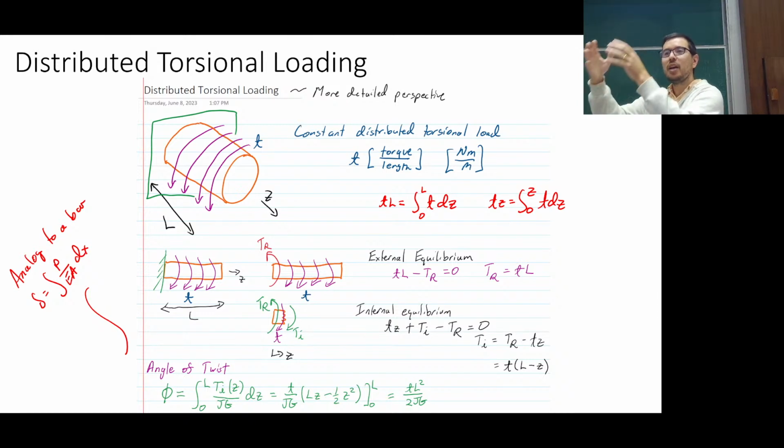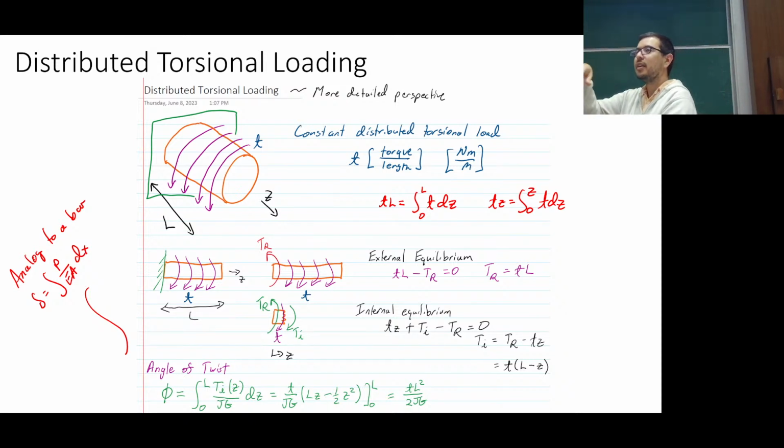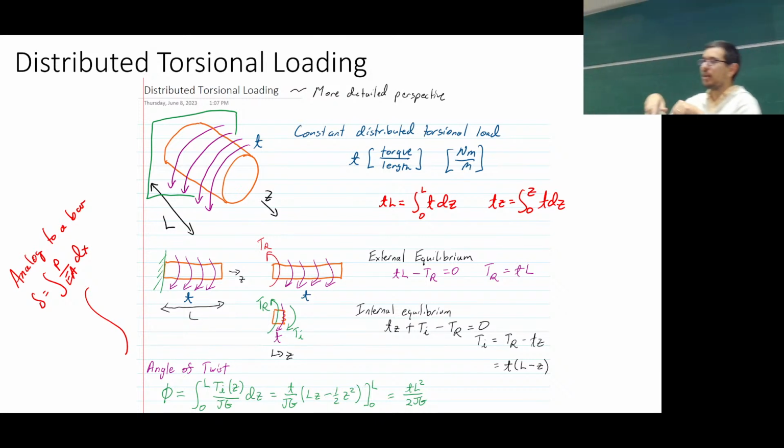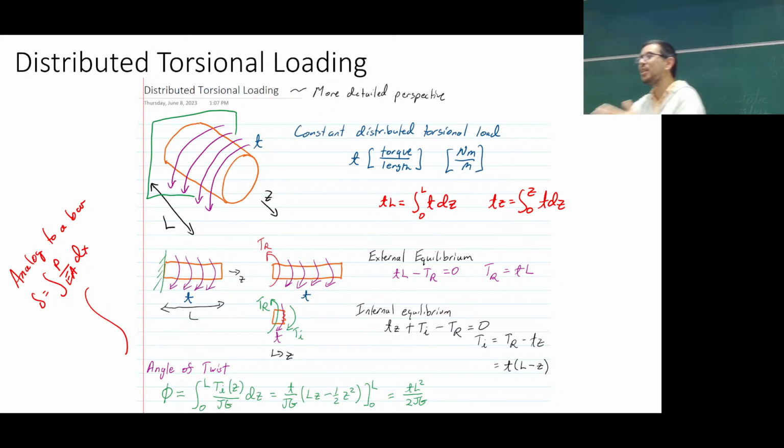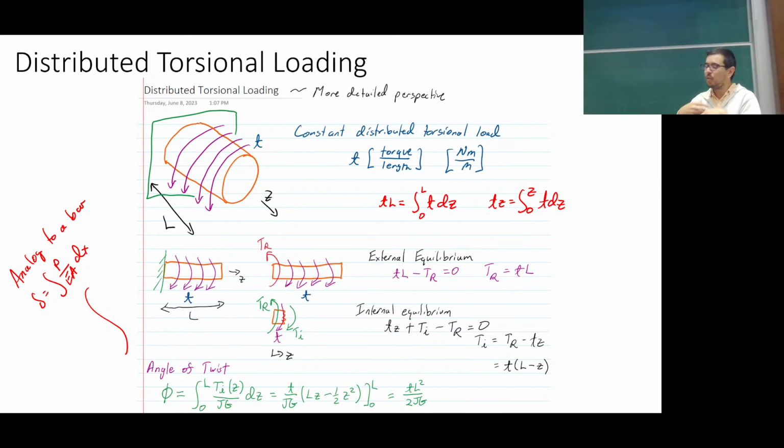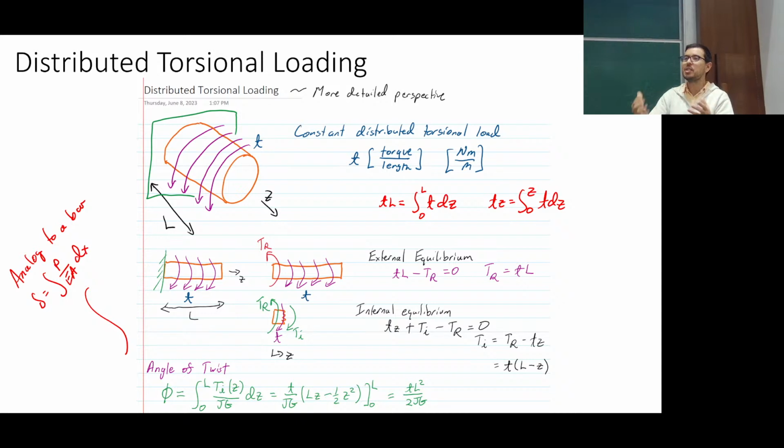If I have a bar, how do I calculate the amount of force that I have to hold it from the ceiling? Yes, Chet. Yeah, you need the length of the bar, yes. You need the weight. Yeah, you want the weight of the bar, just the weight of the bar, right? So it's mg, or it's rho times the volume times g, right? That's what that reaction force is.